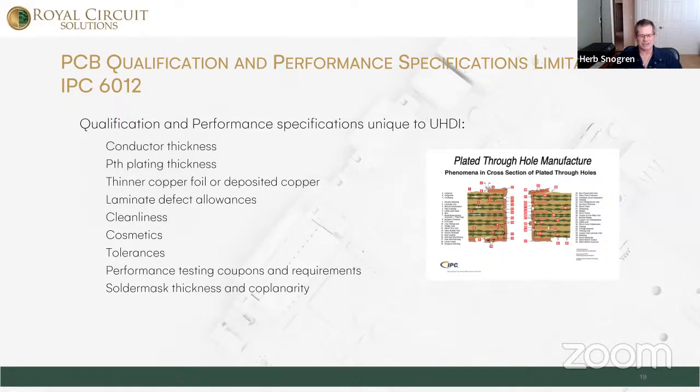As you go down to feature sizes that are 20, 25 microns, people aren't plating those up to a mil thickness typically. They're more at 12 to 18 microns on most boards. So there's a different standard required, I think, for the ultra-HDI conductor thickness. Same with the plated through hole thickness. IPC really doesn't deal with thinner copper foils than 9 microns, so we need to rewrite the standards to apply to thinner copper foils or no foil if we're using the Semi Additive process.